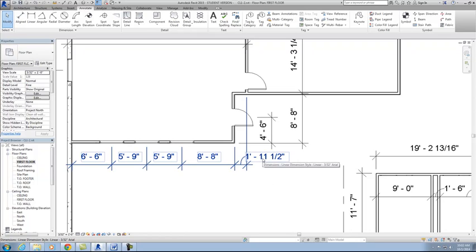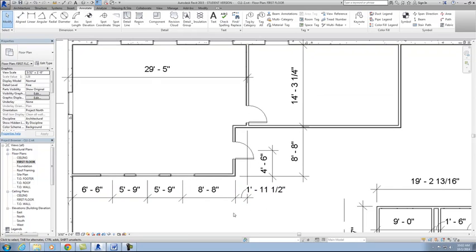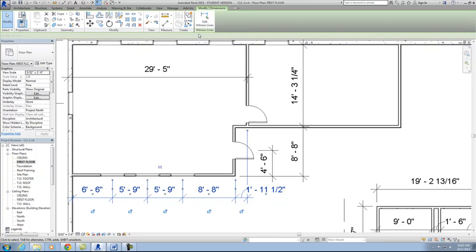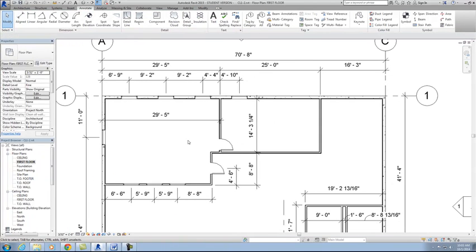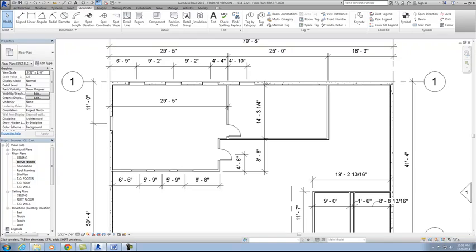Okay. Let's see. I think we're pretty much there. I don't need this extra dimension anymore, so I'm going to go ahead and take that out. So you add dimensions with the edit witness lines. You can also take them away just by clicking where the dimension is located and then just clicking in open space. So this handles this part of the room.